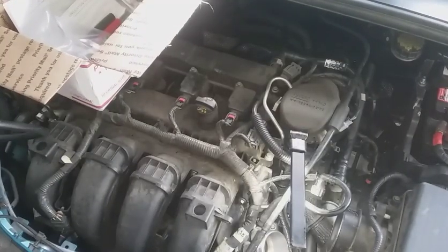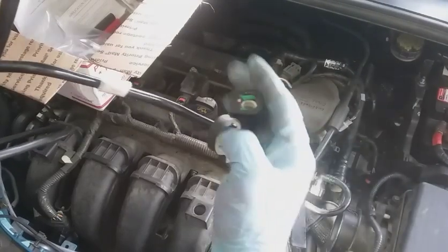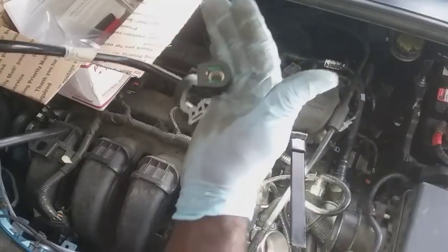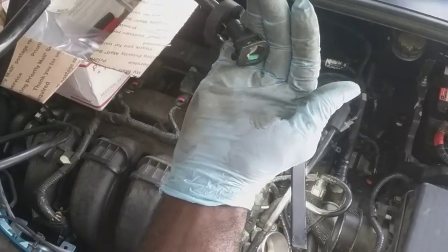It's supposed to be in an off state, and here it is already leaking out. So this is obvious. This purge valve is defective. It's supposed to be off, and it's not. It's supposed to be closed, from what I understand.